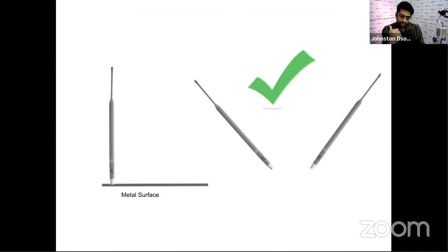Now remember, in-ear monitors, what happens is, in most cases, you are sending a stereo signal out from your console. Okay, so you have twice the amount of power in a transmitter antenna for an in-ear monitoring system. So never keep the transmitting antenna of an in-ear system behind a receiving antenna of a microphone system, because the transmitting antenna is going to blast that receiver antenna with RF, which is not necessary, and you will have poor signal coming in from the microphones then.